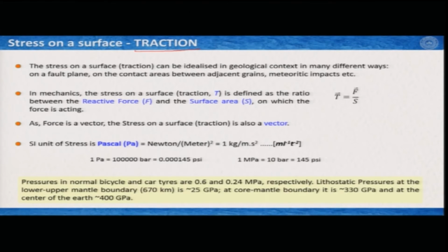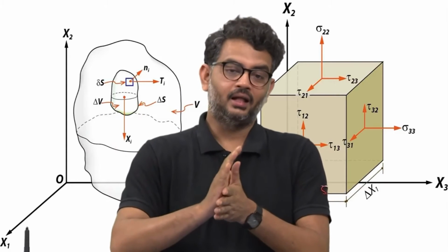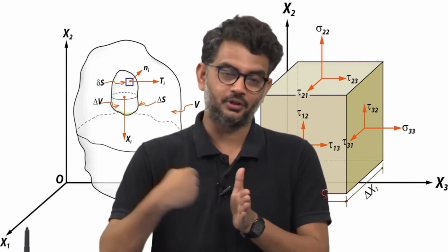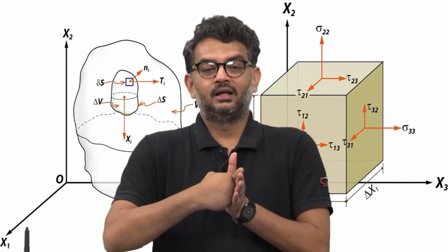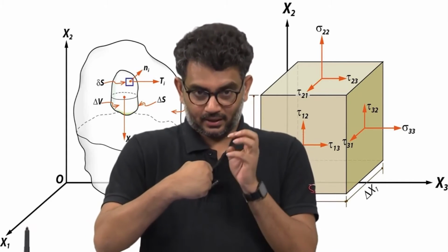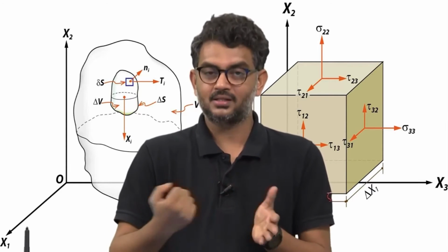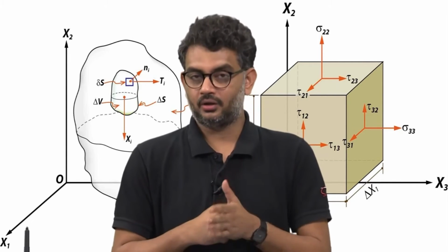So, the definition of stress: generally we commonly say, what is stress? Force per unit area. You are right, but that is not absolutely true. It is actually the reactive force per unit area. That means, if I apply a force here, and I know the magnitude of this force that I am pushing my left palm with this right hand punch, then if I take this force and divide it by the area of my left palm, I will certainly get a value, but that is not stress.